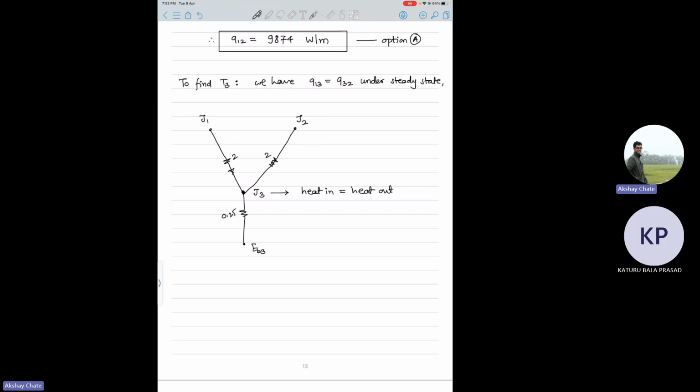So you have to balance these quantities. So whatever is the direction for this one, you need to balance it out. So how do you do that? In case of electrical analogy, you divide the current, right, and then you write it as voltage by R. So here your Q1 to 3 which is coming, and Q3 to 2 is going, and let's say this is your Q3 dash or something like that, is equal to 0, right?